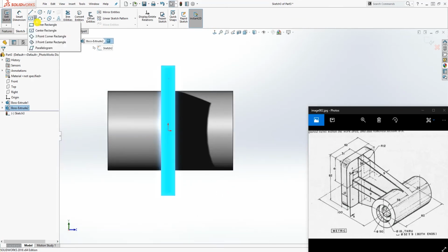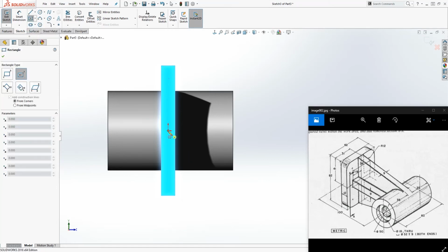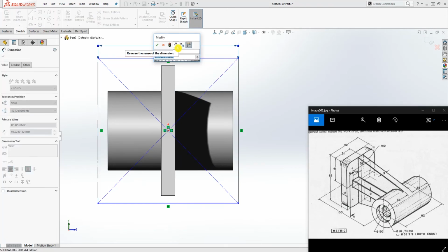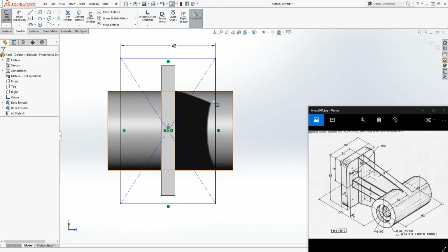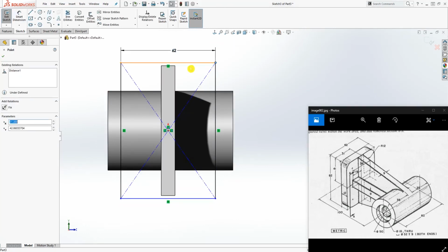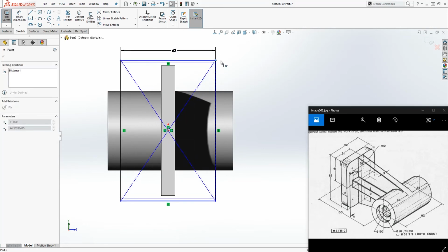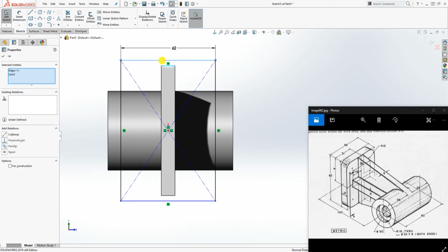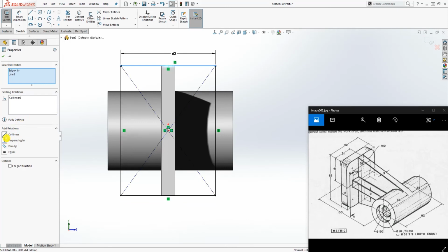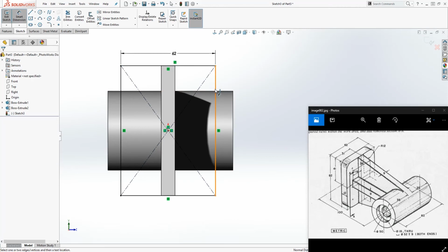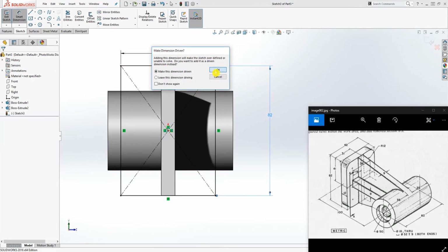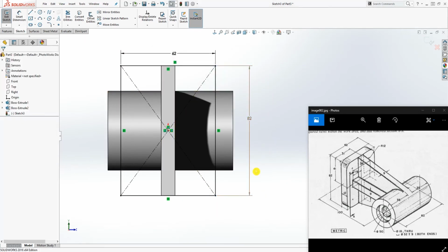So now on the back side, we want to click this face, sketch number 2, and I'm just going to draw a center rectangle, just draw something like that. And we are going to add the dimension here, 62, and the only dimension we need is this coming up and down. So we can just make this line and that line, holding the control key, selecting both lines and making it collinear, because that line is 82. And just to verify it, if I dimension it, you see that is also 82. So I just leave that as a reference dimension, 82.